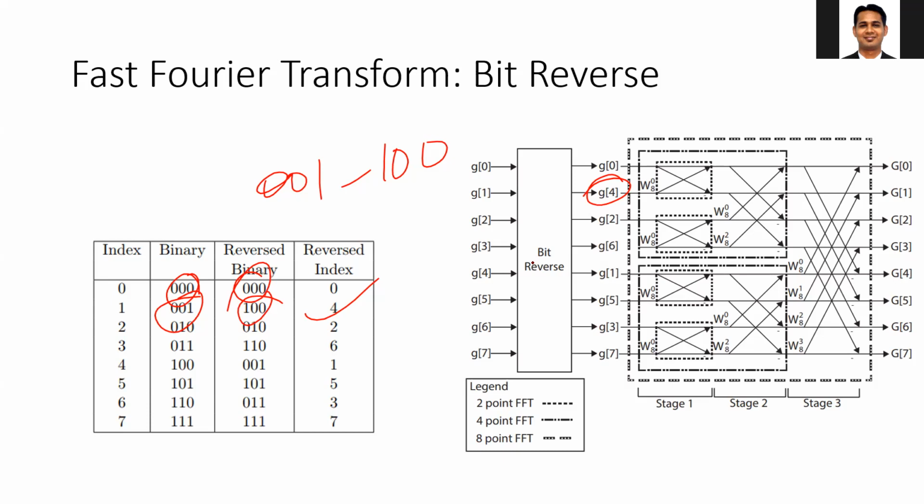In case of the 1024-point FFT, it will be 512. In case of the 16-point FFT, there will be 8 butterflies in stage 1. In each following stage, they reduce by 2, so you will have 8, 4, 2, 1, and so on. The same logic is written in the software implementation.